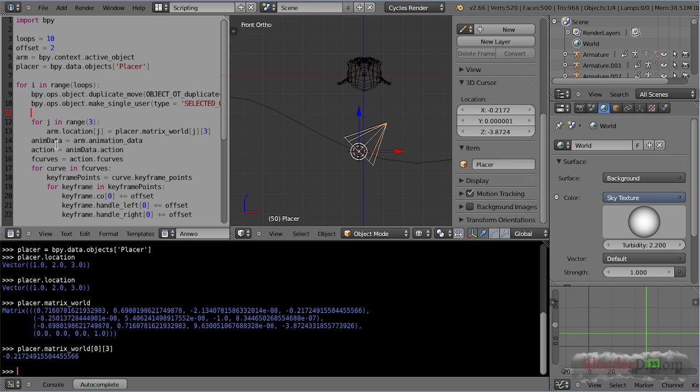The frame_set method has a big advantage because if you're using the current frame equals, that means we are actually jumping to that frame, but Blender is not going to evaluate any animation data. So the scene is actually going to be that frame, but none of the keyframes, none of the path animations, none of that will be taken into account.